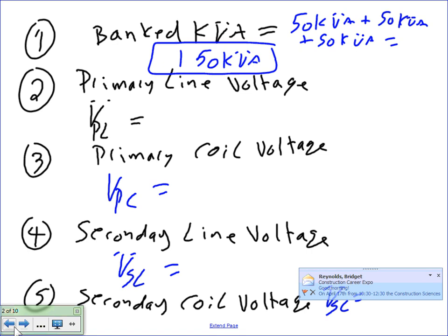When you buy the transformer, once you know it's going to be running in delta, for example, you can hook it up delta or Y, it doesn't matter. But if it's hooked up delta, the current is going to be different. Three times the current. Correct? Yes, considerably more current than a Y through the coil of the transformer.